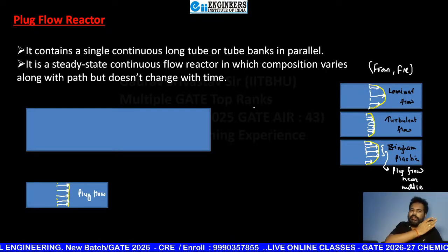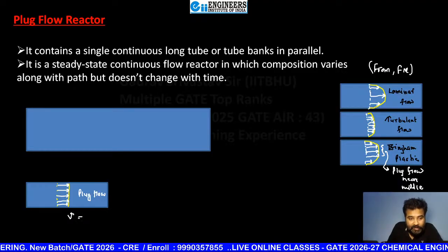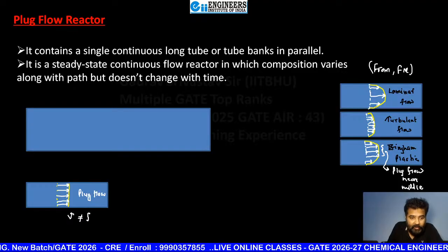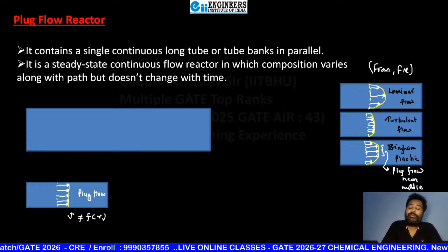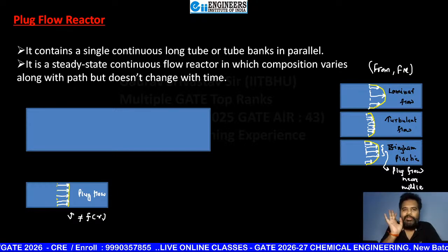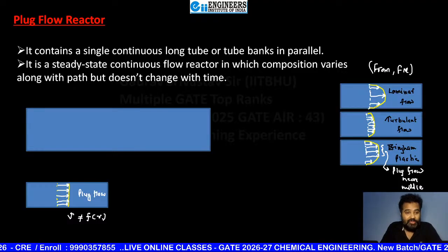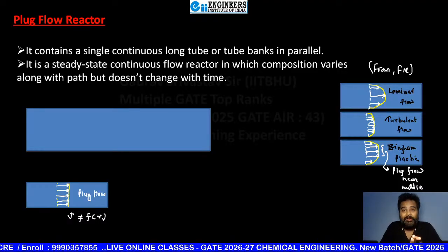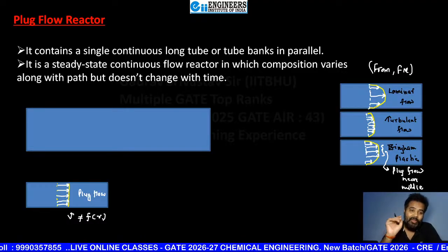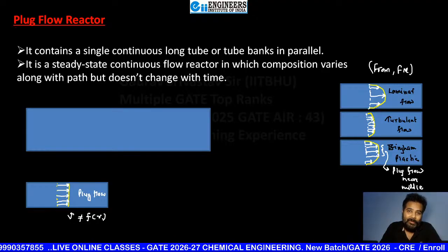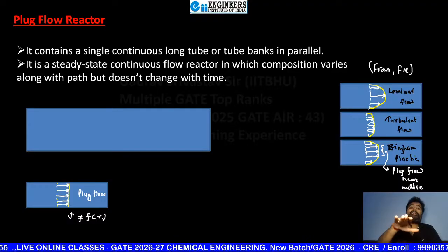So plug flow meaning what? Plug flow means that the velocity is not a function of radius. It is not going to depend upon radius. At any radius, velocity will remain the same, and you know it is not possible in an ideal manner, because no tube is available with zero friction. Definitely some friction is there in the tube, and also at the wall a no-slip condition is there. So if some fluid is stationary, then definitely it is going to resist the sliding layer above.